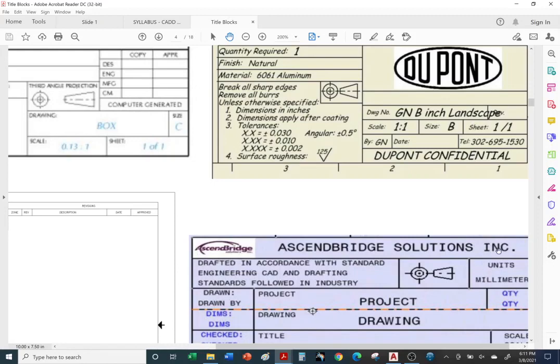You also have to call out the units. So 99% of your drawings in mechanical drafting will either be millimeters or inches. It's rare, but sometimes you will combine the units. One good example is you'll make your entire drawing using inches, but it just happens that the thread of the hardware that you had to order only came in millimeters. So it's okay if you use a drawing all in inches, and the hardware only came in millimeters. You can call that out in the drawing, that it's metric.